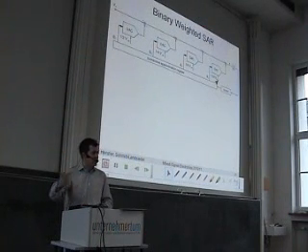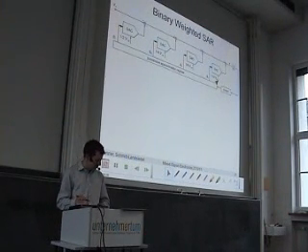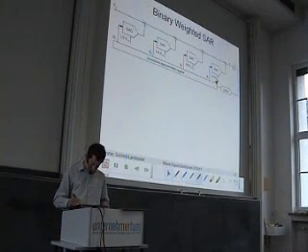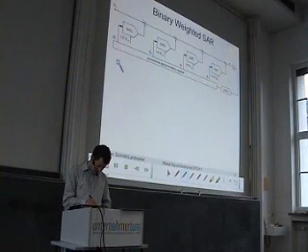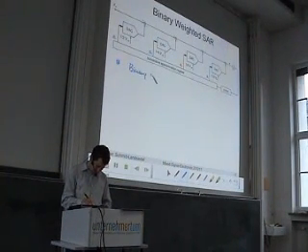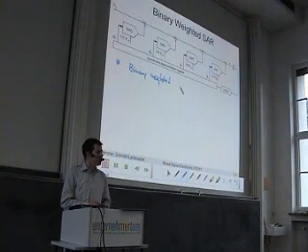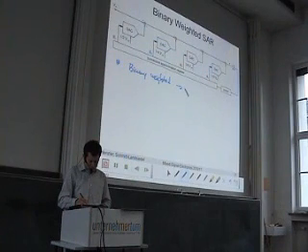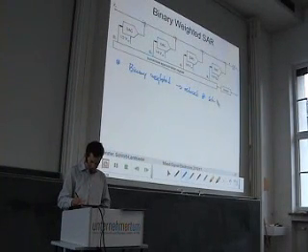And in each cycle, we choose one bit here. So this is a binary coding. So this is desirable to reduce the number of sub-DACs. So we have here a reduced number of sub-DACs.